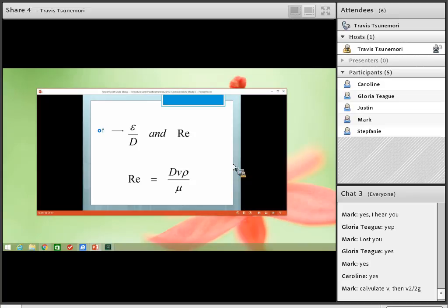We also need, while you're at it, the dynamic viscosity of the air. Perfect. Page 20 in the textbook. We're going to look under air. There's a table 2-1. And if we do air at ambient temperature, the density is 1.202 kilograms per meter cubed. And the dynamic viscosity is 1.82 times 10 to the minus 5 Pascal seconds.